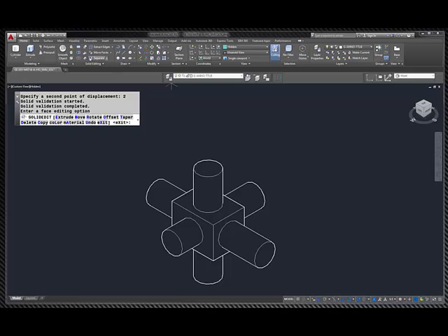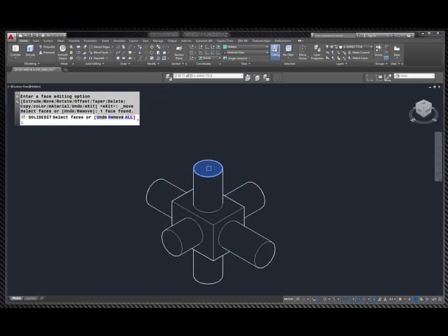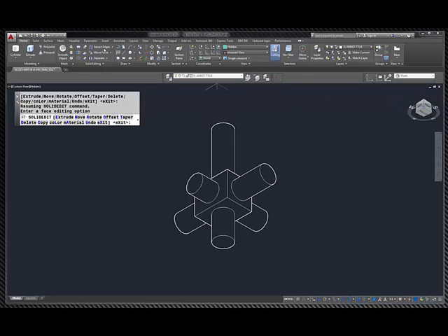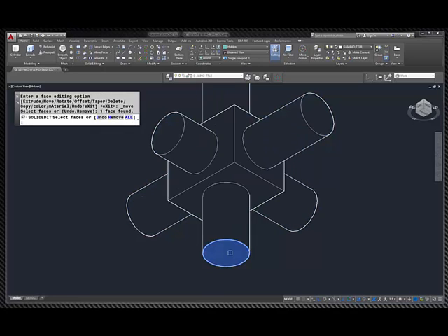And then I'm going to go back up here and move face, and I'm going to pick a piece of geometry. Enter, pick it, and 6. And move face, pick a point. Again, I can come anywhere. I'm just giving it a direction is all I'm doing. Give it a distance.